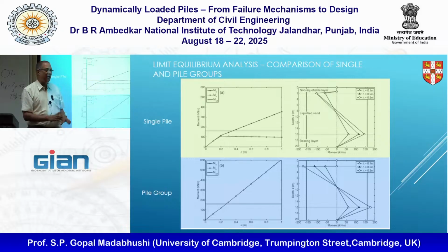Okay? Now we've got the proof, and we can also tell how much deflection it can tolerate. This is all pure structural analysis. We haven't done any magic with this. This is how much structurally I can deflect to get the failure or plastic moment hinge formation.